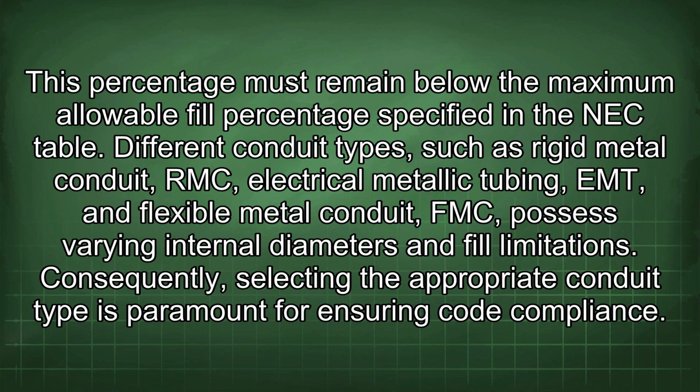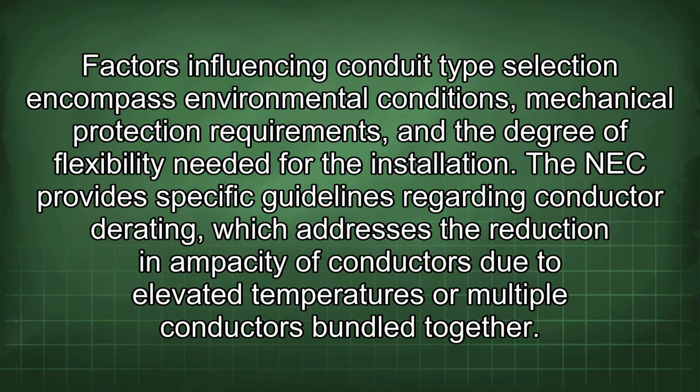Consequently, selecting the appropriate conduit type is paramount for ensuring code compliance. Factors influencing conduit type selection encompass environmental conditions, mechanical protection requirements, and the degree of flexibility needed for the installation. The NEC provides specific guidelines regarding conductor derating, which addresses the reduction in ampacity of conductors due to elevated temperatures or multiple conductors bundled together.